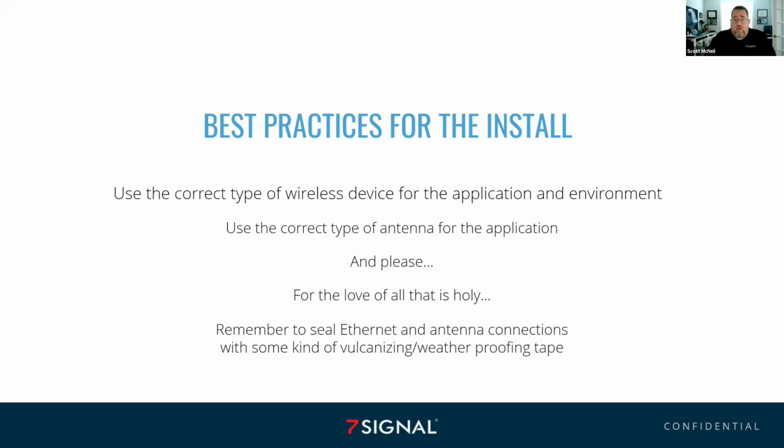But I cannot tell you how many failing installations were failing because nobody took the extra few minutes to weatherize their connections. Everybody knows if you get water in an AP, it ruins the AP, but if you get water in LMR or pigtails, it ruins those too. You get water in an antenna, it's not going to function properly anymore either. They become non-reliable and you have to replace those.